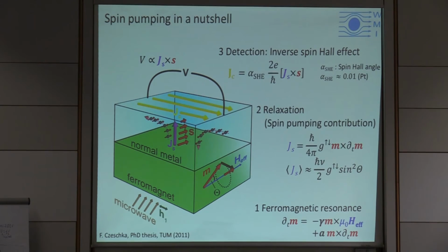The interesting thing is you could make this stripe technically thin and just surf on a stripe width which is smaller than the wavelengths of your surface acoustic wave. That should be possible because the voltage that you generate here is proportional to the length of your stripe and not to the width, to a first instance. You have seen that the pulses that we use here are reasonably high frequency pulses, so we do some 50 ohm magic with the circuitry there, and this makes things maybe more complicated or more involved.